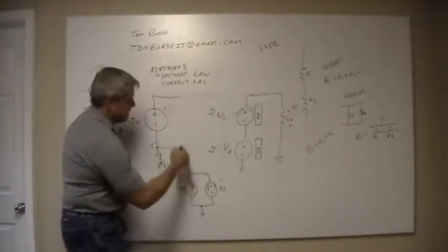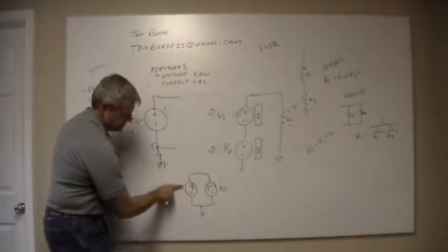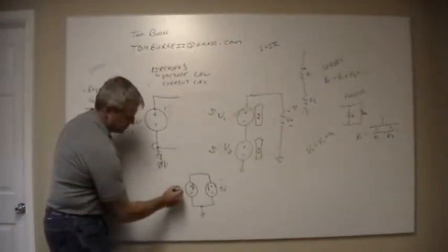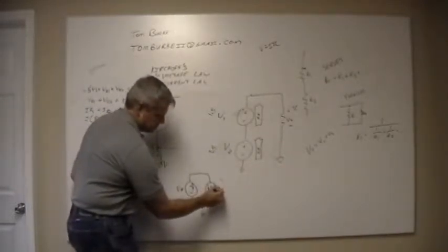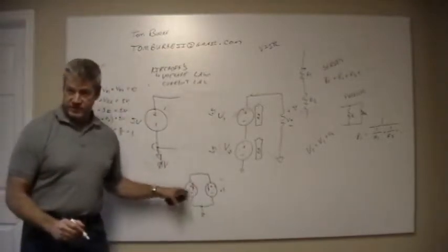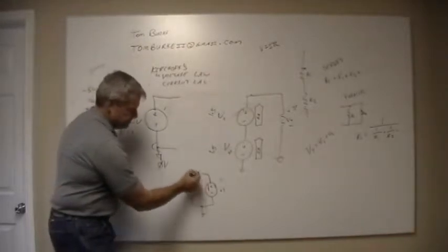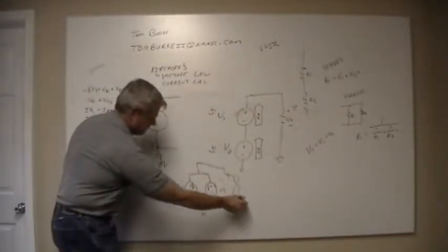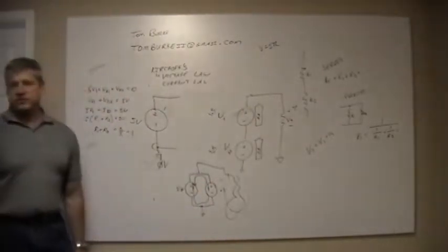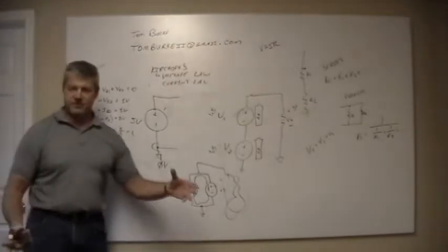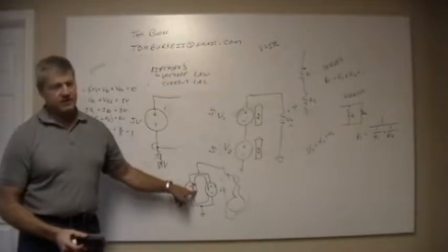Because of Kirchhoff's voltage law, I can look at this as the voltage across the internal resistance there. No matter what my circuit out here is doing, all my current's flowing that way through there, generating heat. Eventually something goes boom, if there's enough current, because those resistances inside of a good power supply are practically a wire.